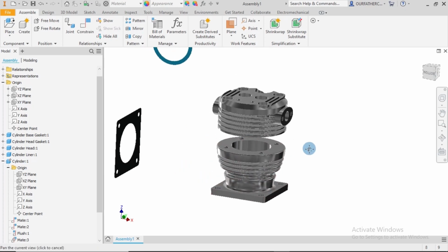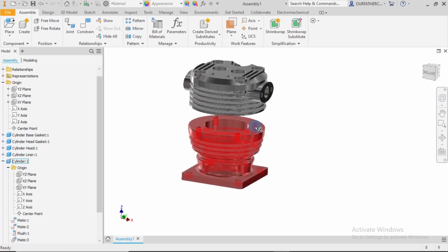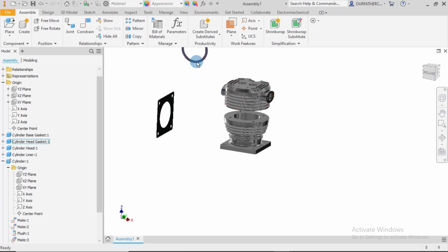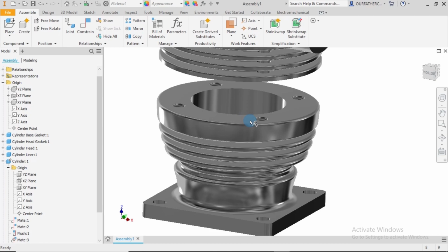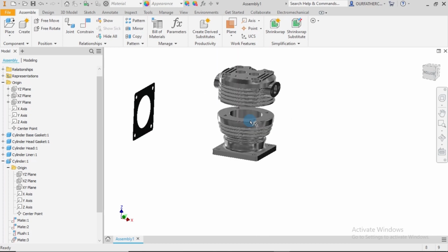It helps to seal the space in between, because when you bring two solids together, based on microstructure, there's still going to be a little bit of space, so fluid can flow out of it. So they bring a gasket which is able to deform and fill in that little space, so that there would not be a leak of fluid.